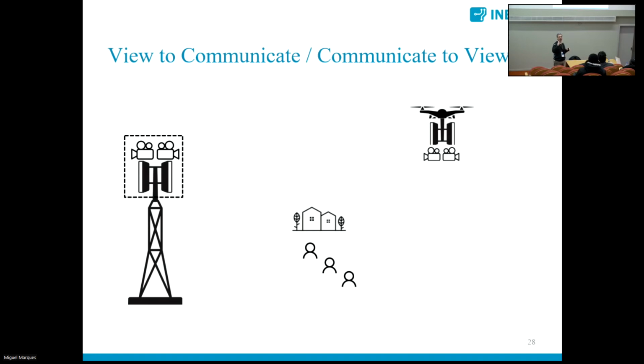For certain frequencies, or very high frequencies, we cannot communicate with nodes that are, for instance, on the other side of the wall, because walls introduce very high attenuations for high frequencies, and so our communications cannot traverse the wall. In some way, communication is limited to what we can see, because if we cannot see our partner, that means that there is an obstacle, and the ray that I'm using to communicate, a ray like this, will not traverse that.